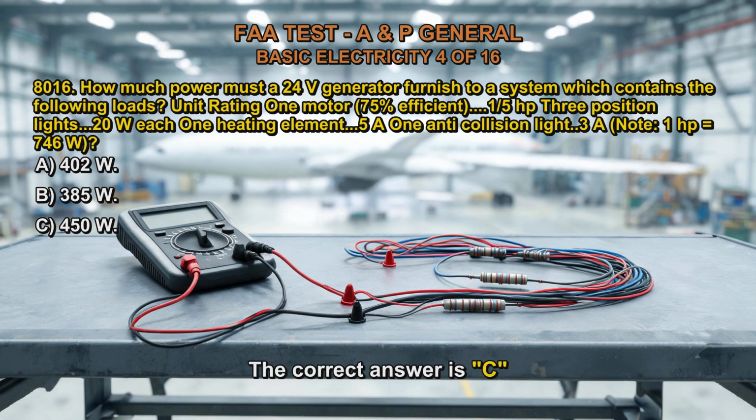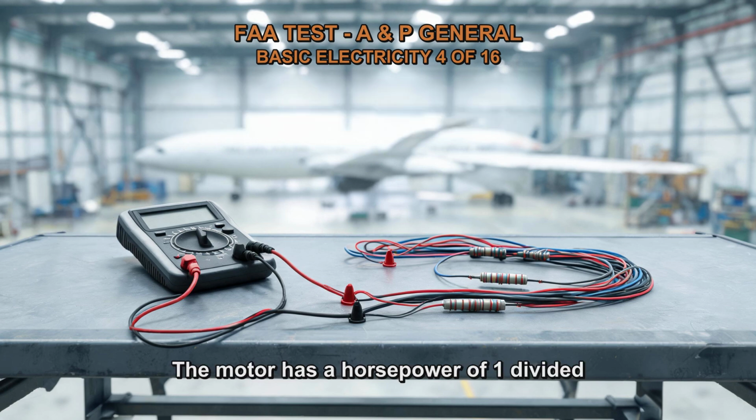The correct answer is C. The motor has a horsepower of 1 divided by 5, and 1 horsepower is 746 watts. 746 divided by 5 is 149 watts. This is the motor output. The efficiency rating can be used to calculate how much additional energy is required to create 149 watts. 149 divided by X equals 75 divided by 100. X equals 199. Therefore, 199 watts are needed for the 1 divided by 5 horsepower motor with a 75% efficiency.